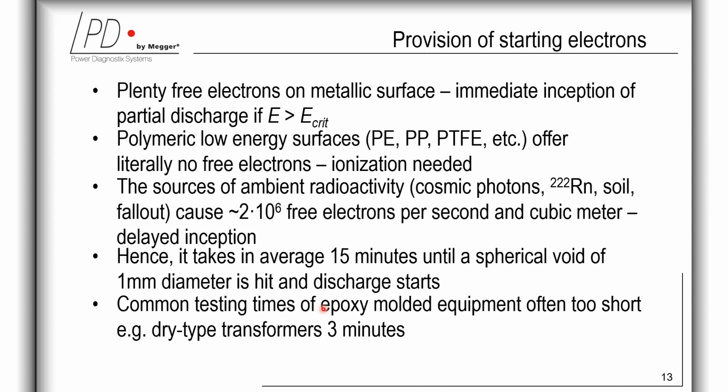Therefore, this makes clearer the standard testing times. For instance, the common testing time for dry type transformers is around 3 minutes. So it's around 1/5 of this mentioned statistical 15 minutes. So it's too short.